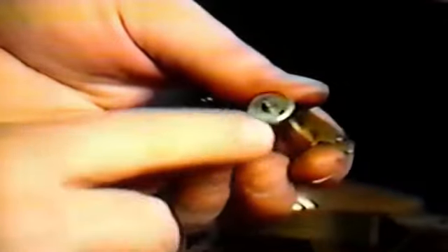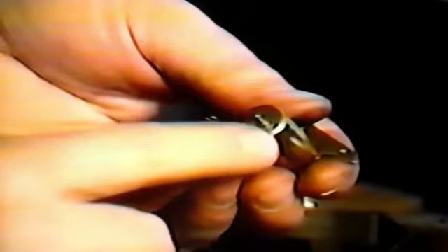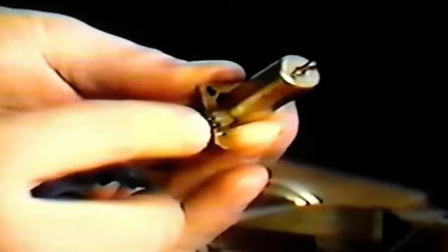You'll be looking for any one or a combination of the following 3 problems. If you find any of them, you should replace the MCS. The first thing to check for is a small hole in the bottom of the solenoid unit. Look inside for small chunks of insulation. In extreme cases, these chunks of insulation may have entered the carburetor and fouled the system.